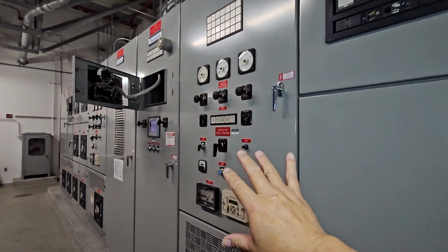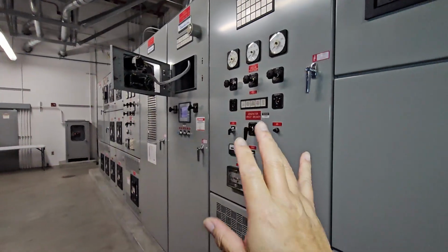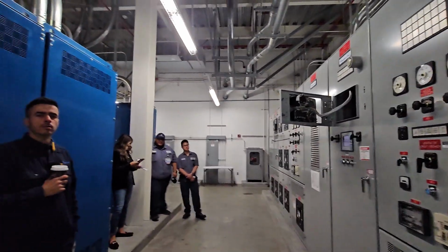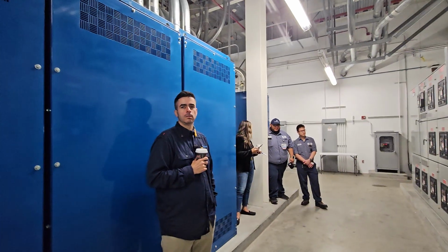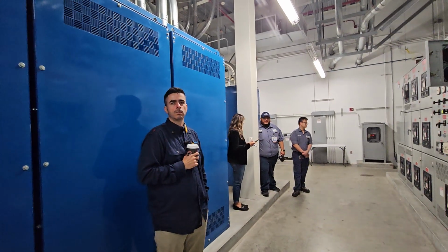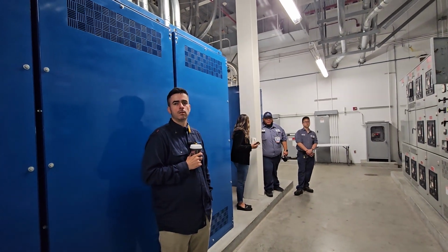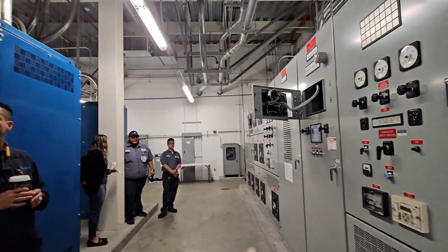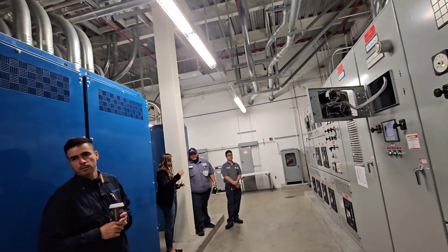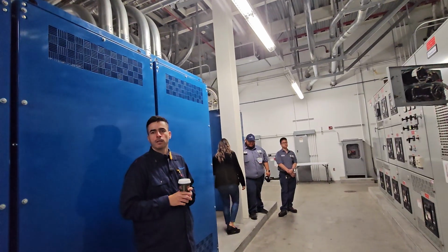This one is manual. You cannot do auto. Now you do manual. So we got the SE back online, so we have to manually switch the ATS back to SE power to get all the load. Only if you have a problem at the ATS. Oh, if it has power, it's automatically switched.